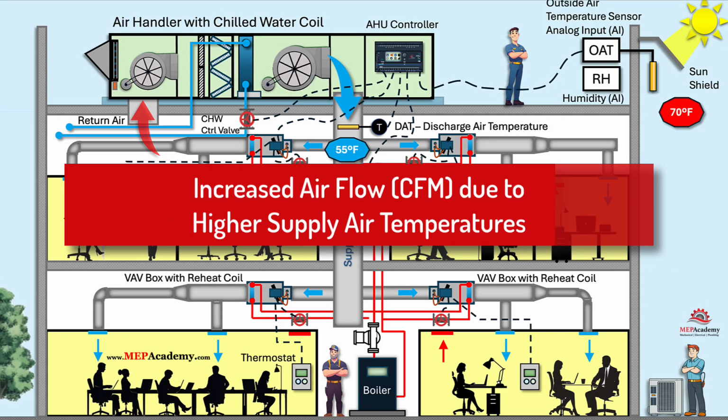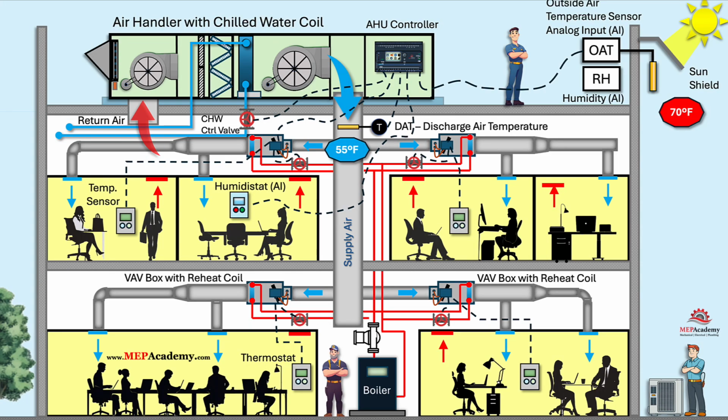To maintain the same sensible cooling capacity, airflow, CFM, must increase as delta T, the temperature difference between supply and room air, decreases, potentially overloading fans and ductwork.